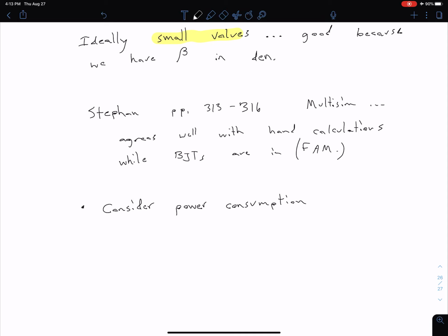So in some cases we might need to have some type of heat sinking abilities. That can take the form of external heat sinks, so maybe we have some type of fins connected to whatever device is absorbing all this power. We'll talk in our next video about how that's done for IC regulators. Or maybe you have to have some type of fan.